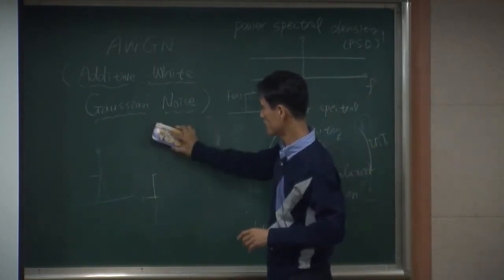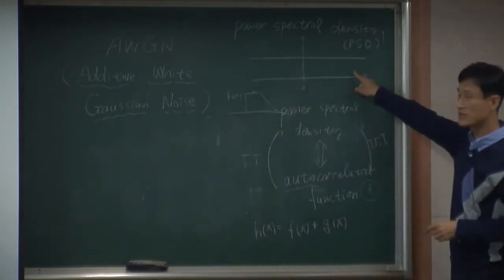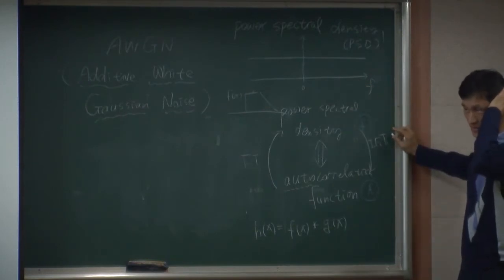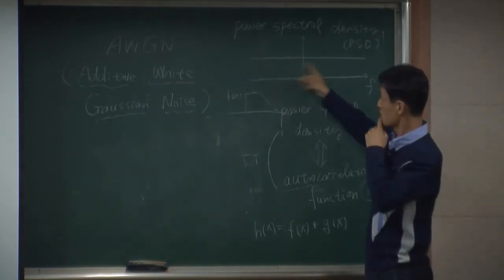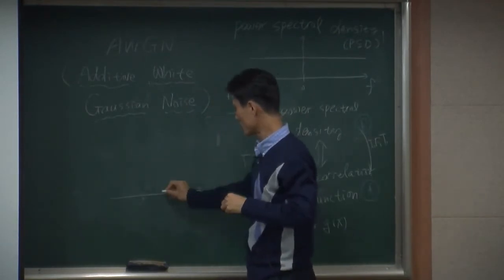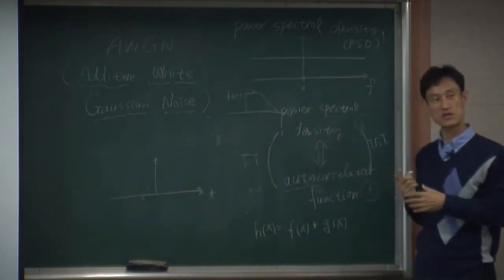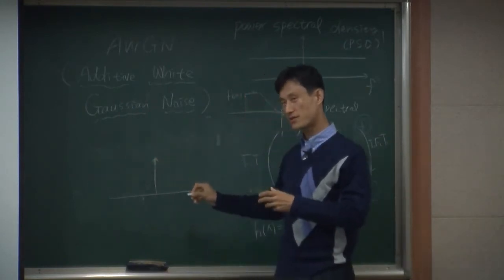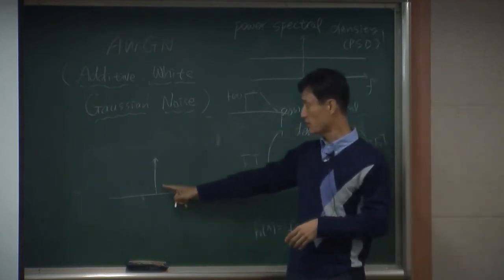What is the inverse Fourier transform of that? Let's say in frequency domain you have this graph, and let's take an inverse Fourier transform. What do you get? In frequency domain, flat. So in time domain, you're going to get a delta function. That's the relationship of a Fourier transform, right? Because in frequency domain we have this, with the inverse Fourier transform, in time domain we get this.